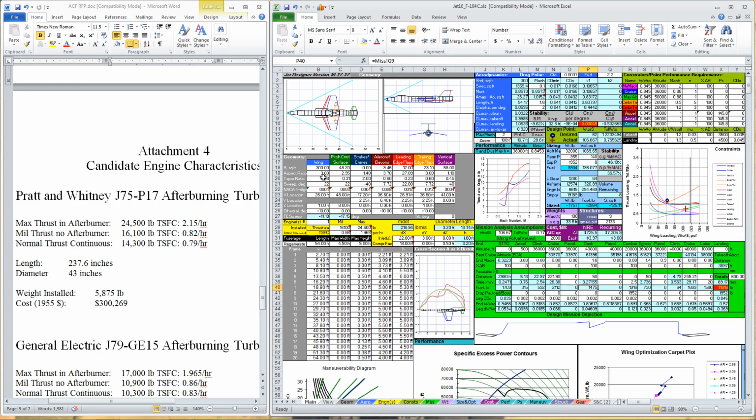So let's sweep the wing more to help it go faster. Let's go to 30 degrees of sweep. Oh, that cut everything. That cut the fuel burn quite a bit. Let's go 40 degrees of sweep. That cut the fuel burn even more. We're just 1,000 pounds light on fuel, and we're almost making the turn constraint.